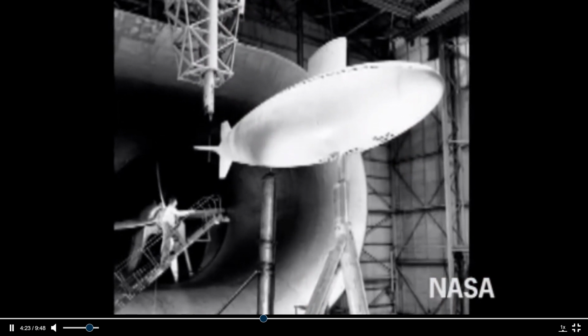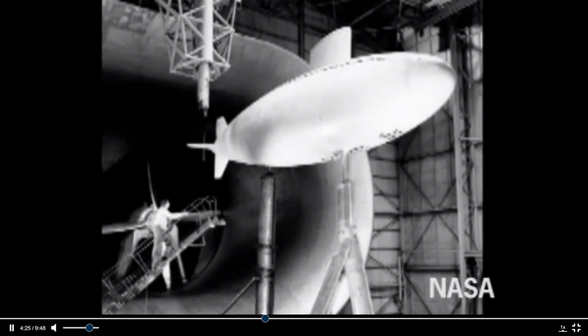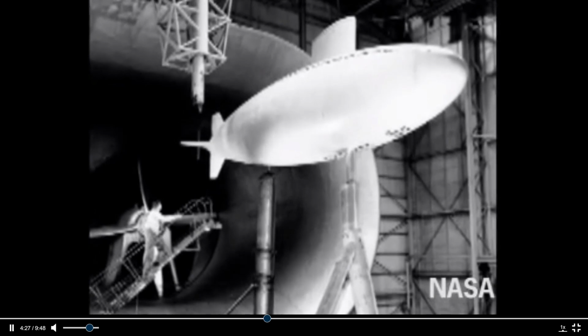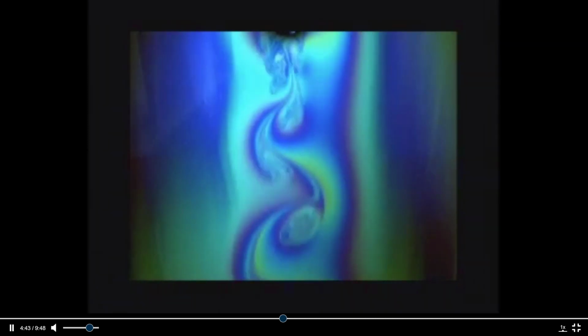Depending on the Reynolds number, some flows have different regimes with different flow patterns. The classic example is the flow over a circular cylinder, illustrated here using a soap film tunnel. At low Reynolds numbers, between about 4 and 40, attached vortices form behind the cylinder. Above about 40, we see the famous Kármán vortex street, the alternate shedding of vortices from one side of the cylinder and then the other.